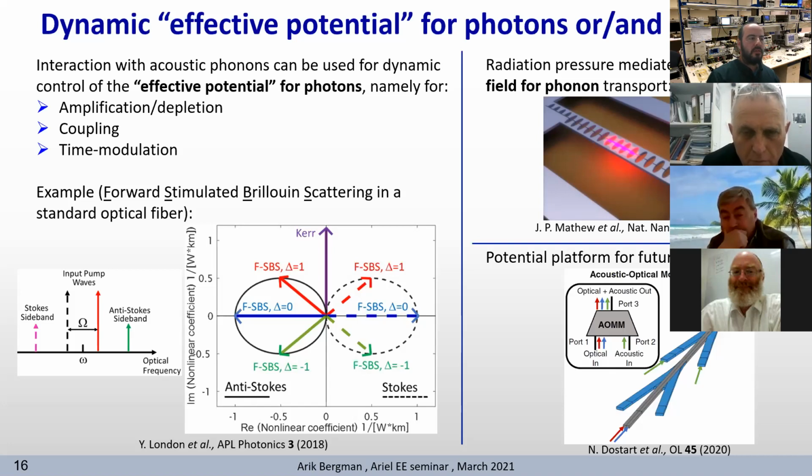I also recently noticed a publication where they show the design of a mode multiplexer in silicon for both guided optical and acoustic waves. Such a platform can efficiently multiplex electrostrictively or photothermally excited acoustic waves, and potentially support future studies of mixed photonic and phononic states in Brillouin active waveguides.